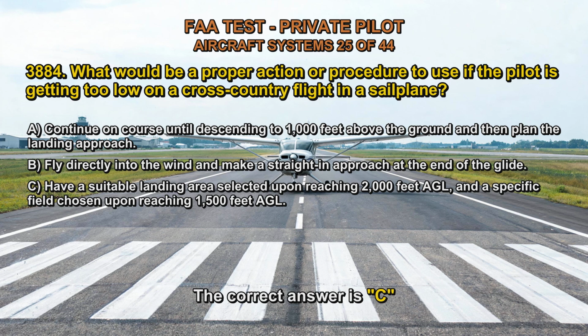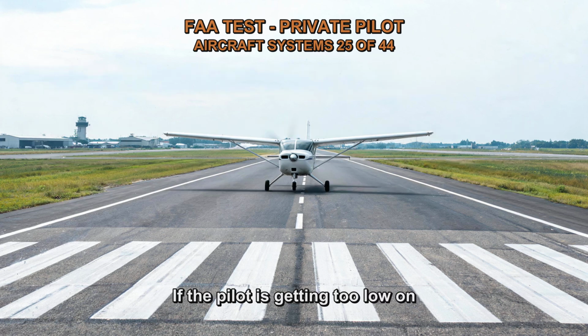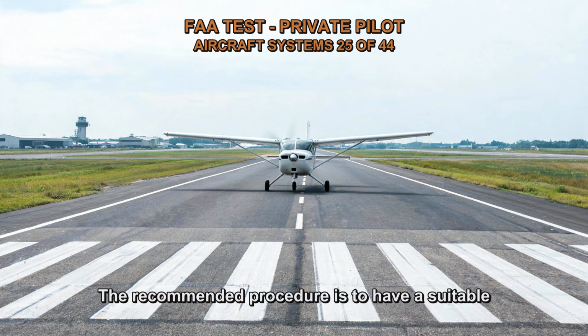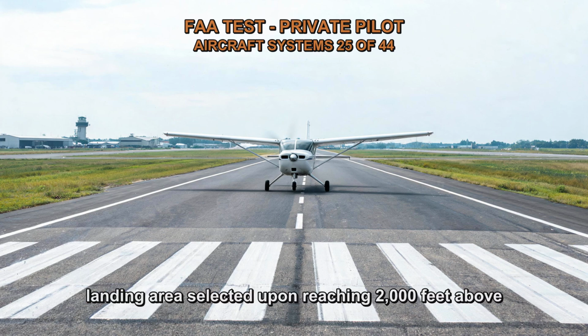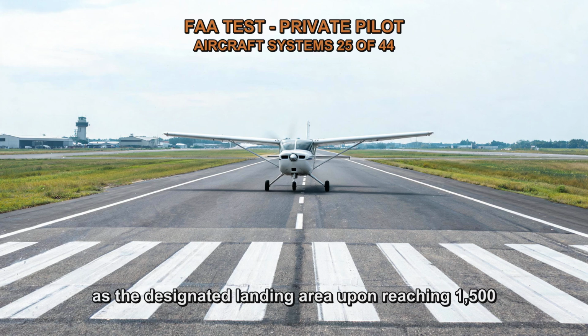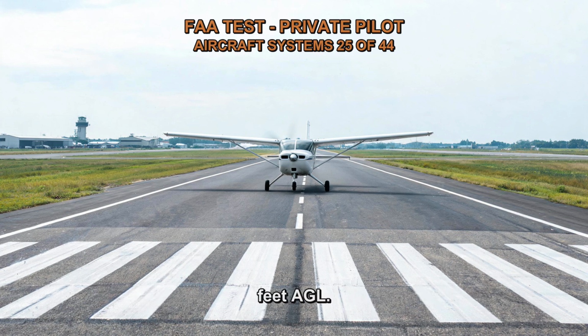The correct answer is C. If the pilot is getting too low on a cross-country flight in a sailplane, it is important to have a proper action plan. The recommended procedure is to have a suitable landing area selected upon reaching 2,000 feet above ground level, AGL, and choose a specific field as the designated landing area upon reaching 1,500 feet AGL.